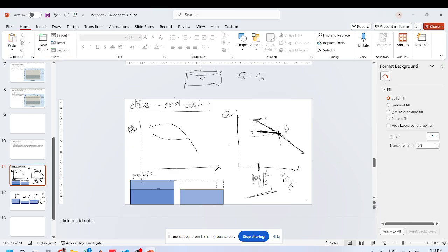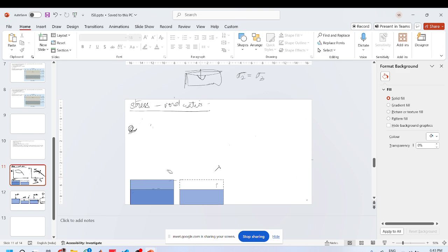And as soon as this point has crossed, it will start moving like this again. This is the volume change characteristic typical to soils, that they remember the loading that they have experienced in their past. The soil has a memory of its stress history, we say.